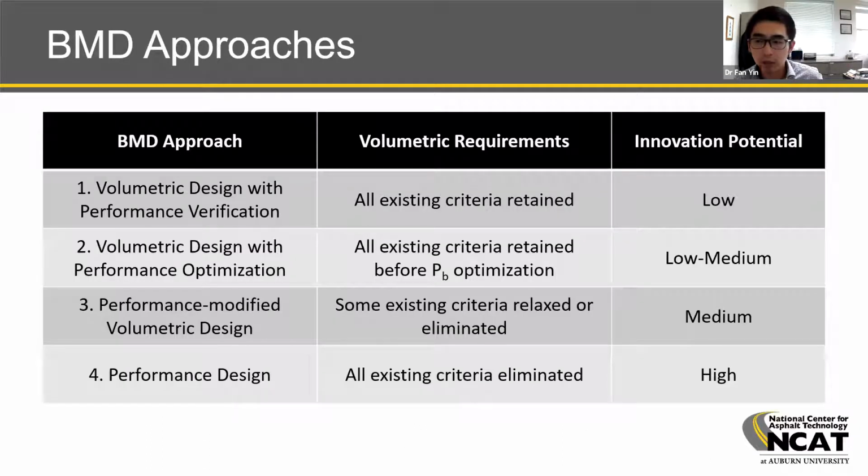Right now, there are 4 different balanced mix design approaches. The difference between those 4 are how we require those volumetric parameters, and also what is the innovation potential. Okay, I don't have time to explain in detail about each approach, but right now, those are the 4 approaches that have been recognized in our industry. And eventually, we want to go to the 4th approach, the true performance design. In this approach, we want to rely on the performance testing result to make the decision in terms of mix design approval and production acceptance, because those performance test results have better correlation to field performance than the volumetric parameters.